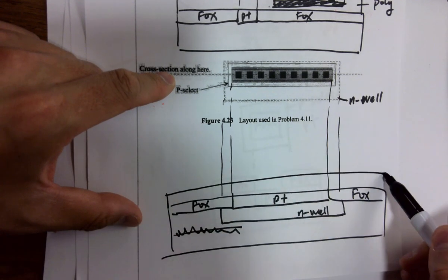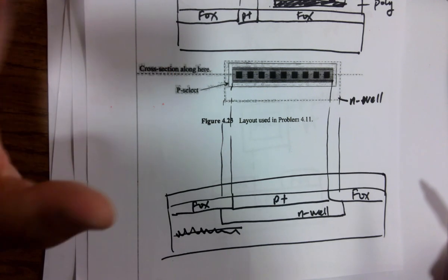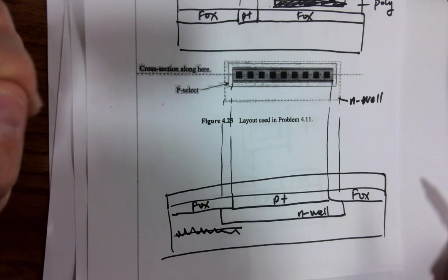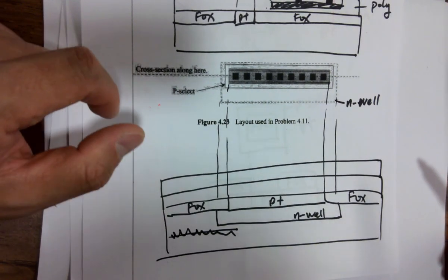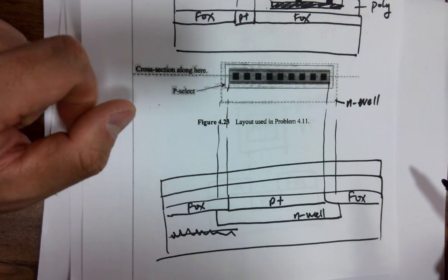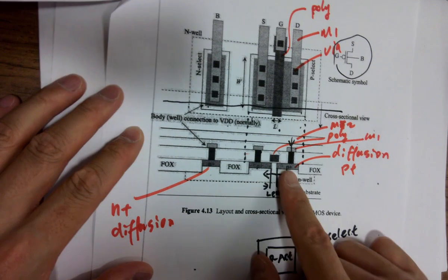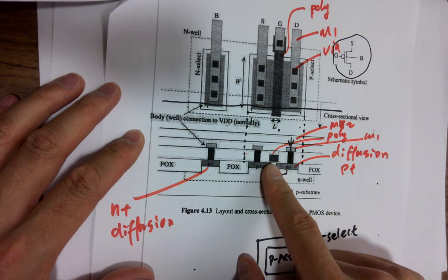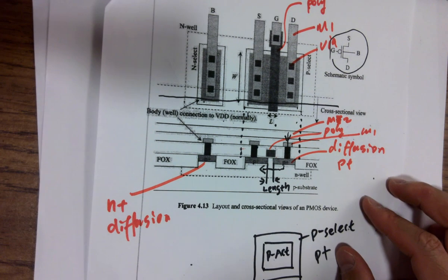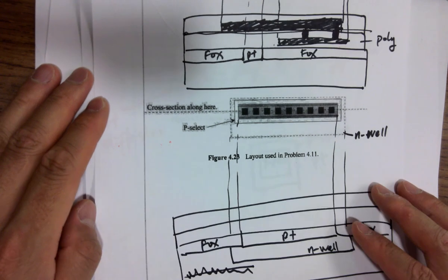So I have no poly, right? No poly. So then you look at the little bars that are next to it. Do you need the poly in the middle as a bridge to make the connection between P plus to metal 1? No. You could just have a bigger via, longer via. Since you have a via, usually there will be metal 1.